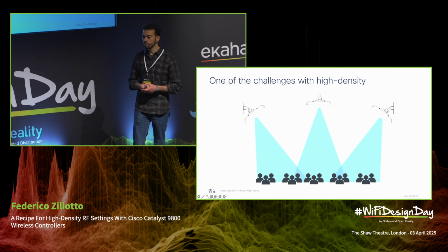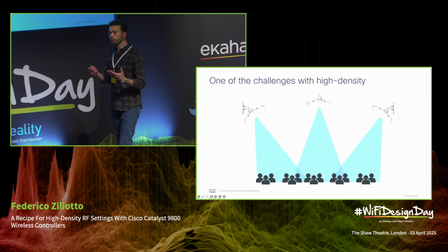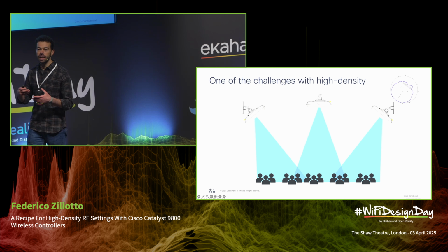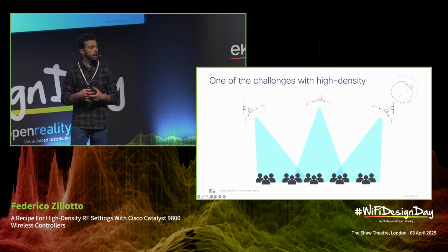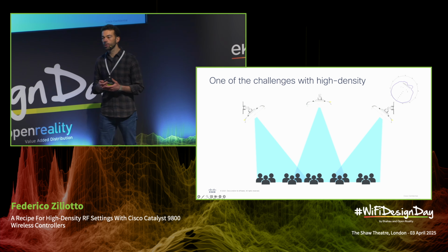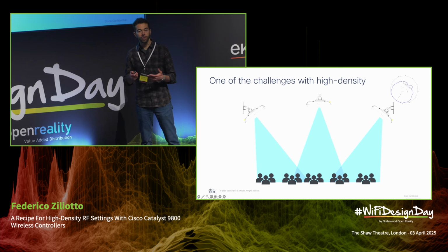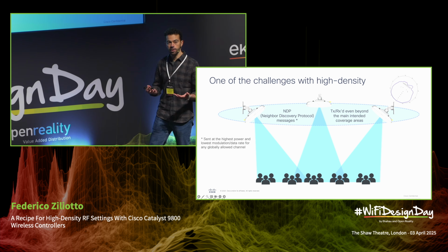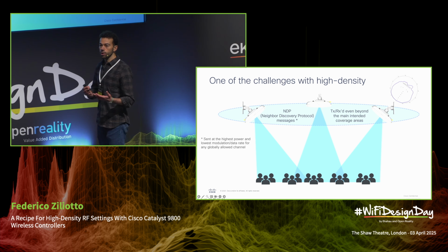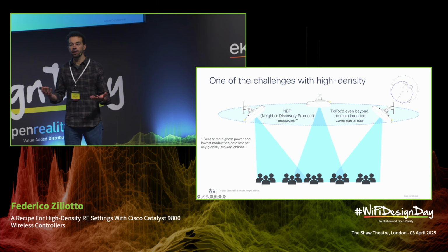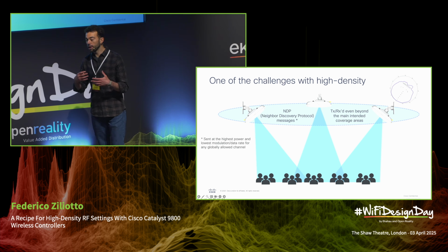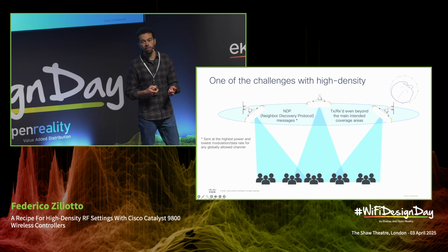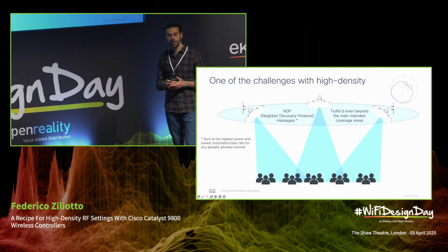Now, as mentioned, Wi-Fi is never a perfect shape, so those directional antennas have, of course, side lobes. We're actually sometimes taking advantage of those leakages and side lobes for the access points to exchange some neighboring messages and to synchronize with one another. Depending on the solution, we call those messages in different ways, but they are useful for the access points to sync up and to do automatic channel planning, transmit power assignment, etc.